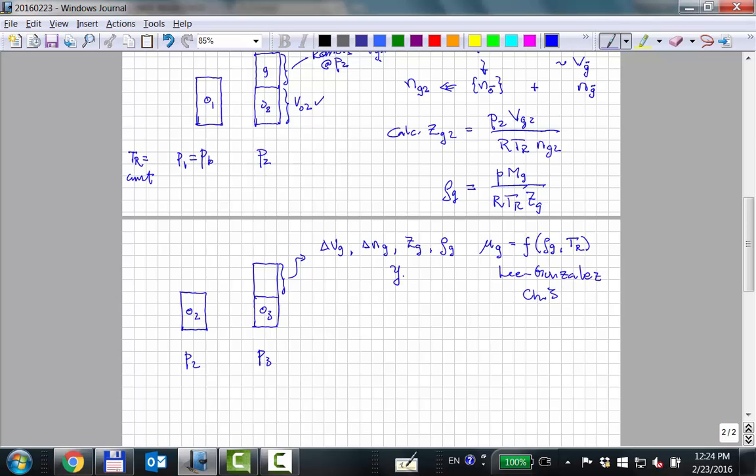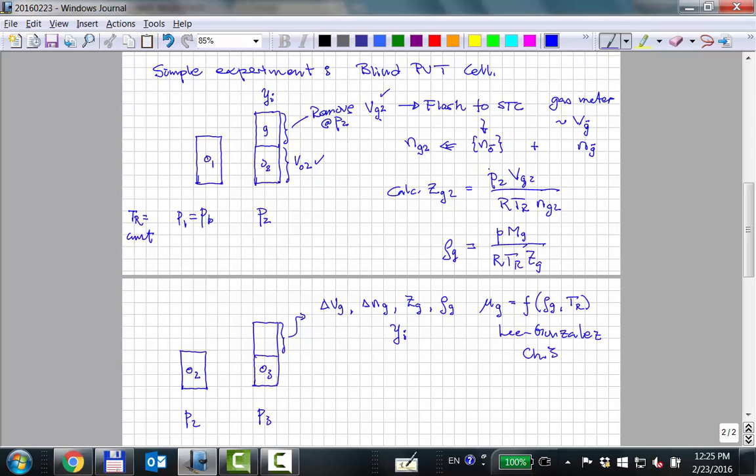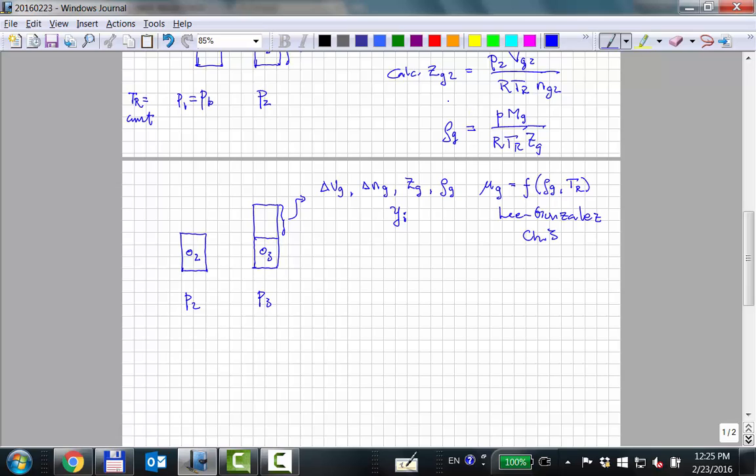We also, in today's PVT reports, you'll get the composition of that gas. Now, one of the problems we alluded to last lecture was that when they flash this gas to the surface conditions, they either ignore or they don't collect all of the liquid that condenses out. So basically this is a big uncertainty in getting that right in the laboratory. The laboratory is not really set up to do this properly, to get the exact gas composition.